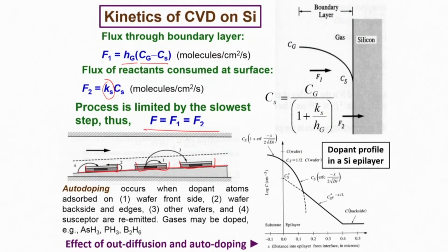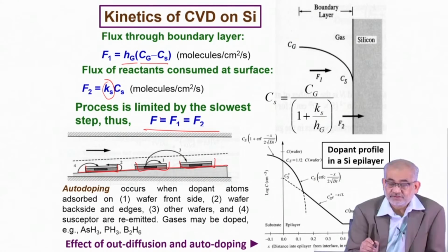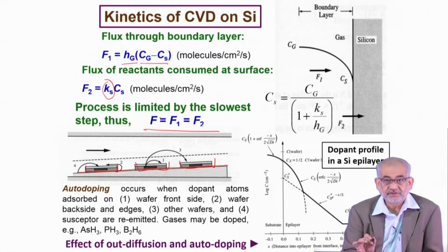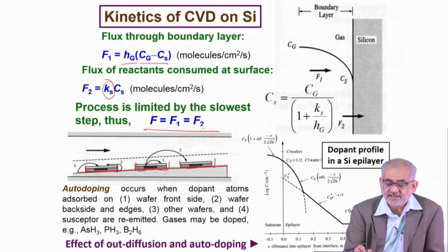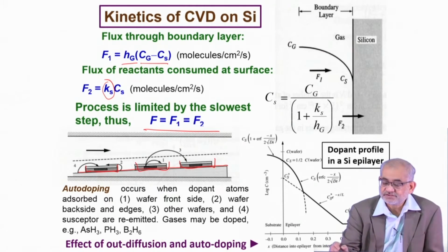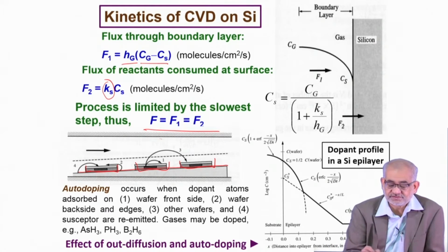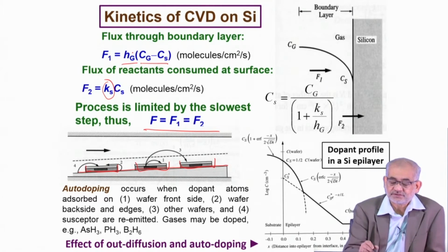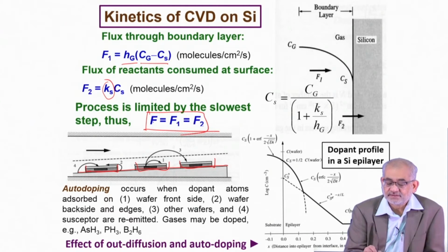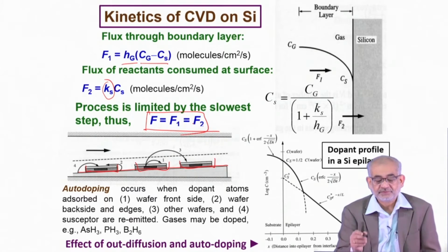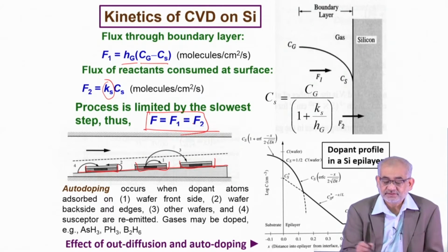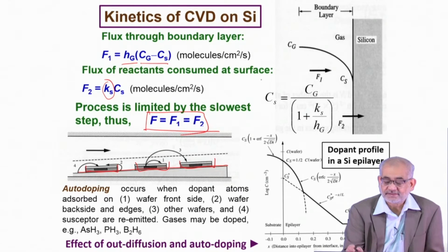The overall flux, when the situation is controlled very optimally, will be equal both away from the substrate surface and very close to or onto the surface, because one of the steps, which could be due to partition coefficient, the convection or the concentration, will make this condition valid: that the flux will be equal both away from the boundary layer, at the top of the boundary layer, or at the surface.